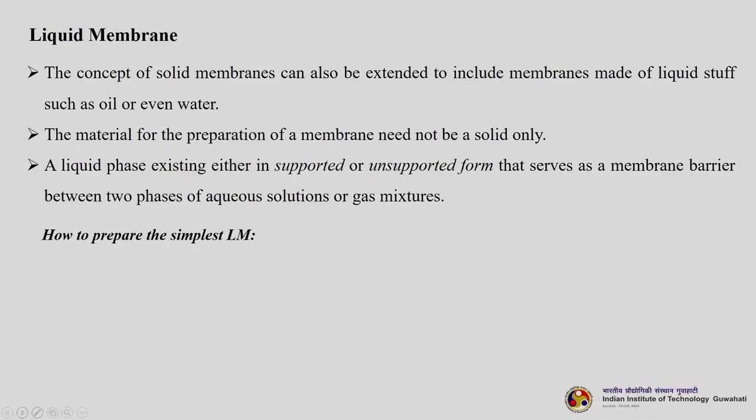So, let us begin. A liquid membrane is, as I told you, nothing but a membrane which itself is a liquid. The concept of solid membranes was extended to include membranes made up of liquid stuff such as oil or even water or any other organic solvents. The material for the preparation of a membrane need not be a solid only. A liquid phase existing either in supported or unsupported form, we will see and learn what is the meaning of supported and unsupported, serves as a membrane barrier between two phases of aqueous solutions and gas mixtures.